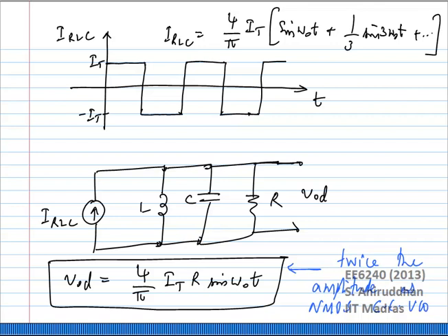You can easily get, depending on how you choose the bias current and the size of the inductor, or the effective value of the parallel resistance, a few hundred millivolts or maybe more than a volt. That is very straightforward. And you can increase this to 0 to VDD. You can make this smaller if you want. You can manipulate this very easily, depending on what you need at the mixer.